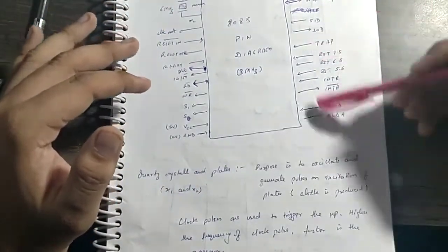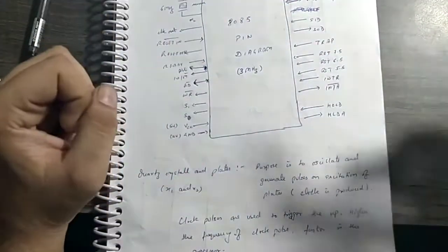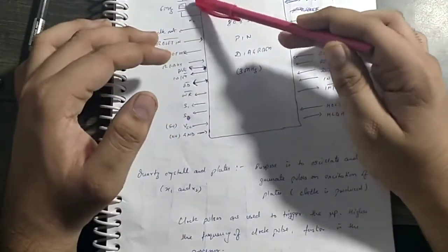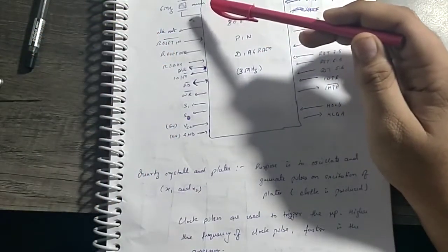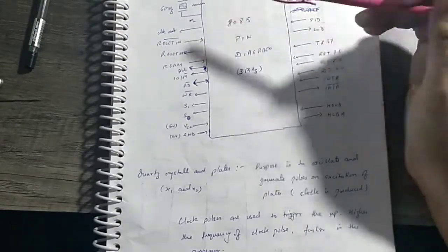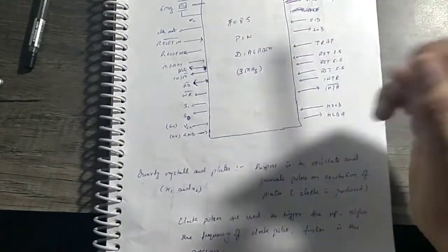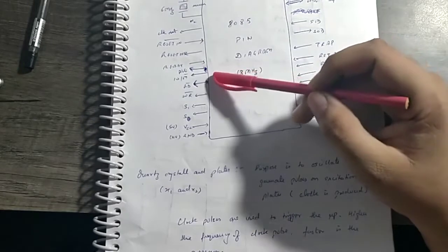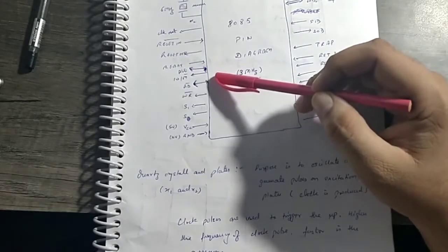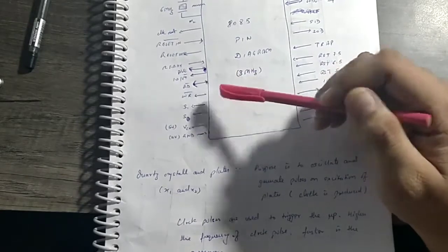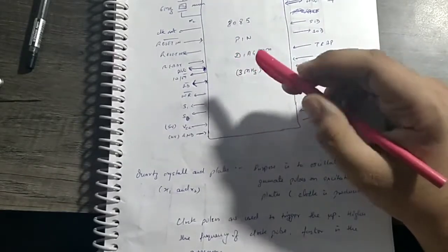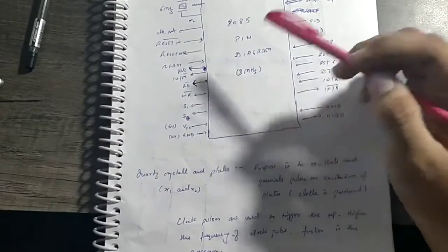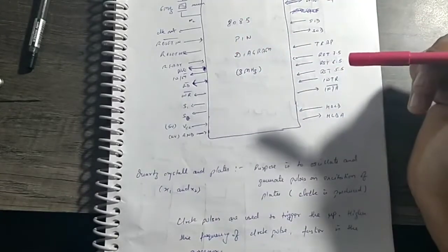By this, we cover the complete 40 pins. So just a quick revision of all these pins. X1 and X2 are crystal oscillator pins, which are used to give the clock pulse. Then we have clock out to give the clock to other devices. We have reset in bar and reset out. We have ready, we have ALE, we have IO/M bar to tell whether it is an IO operation or a memory operation. Then we have read bar and write bar, which are the control signals and not actually the read and write operations, both of which are active low signals.